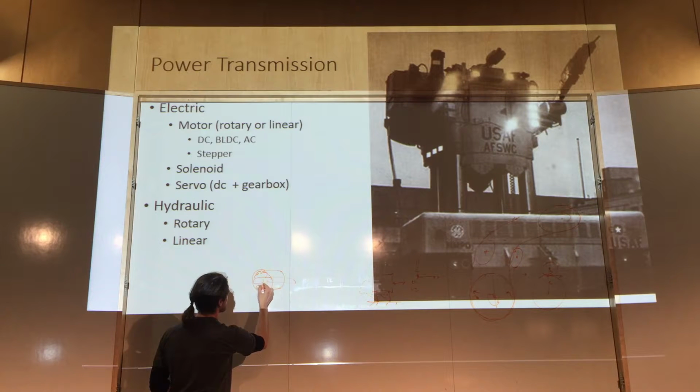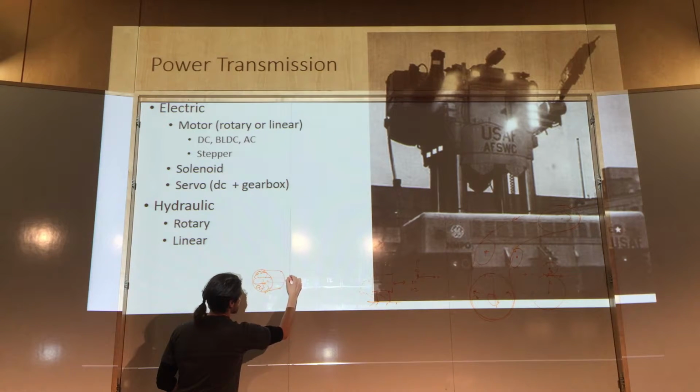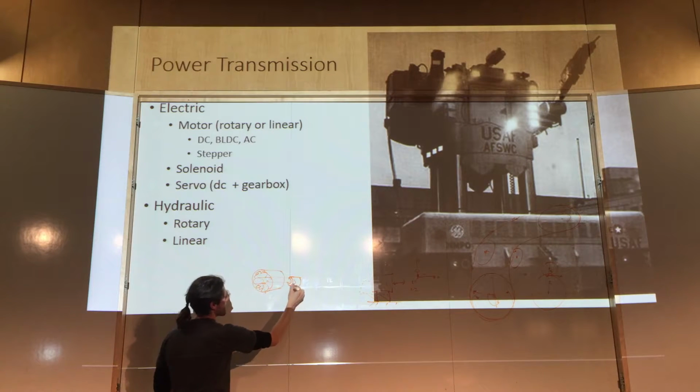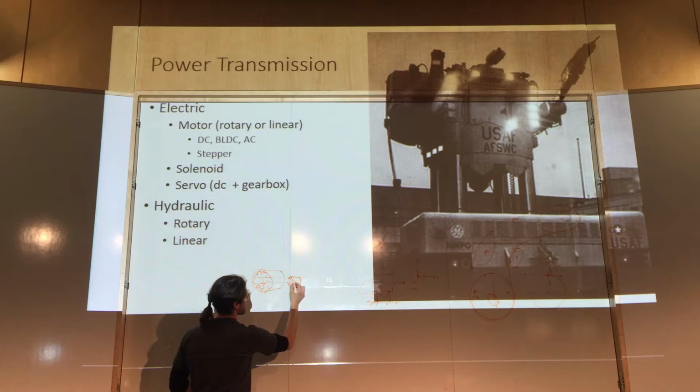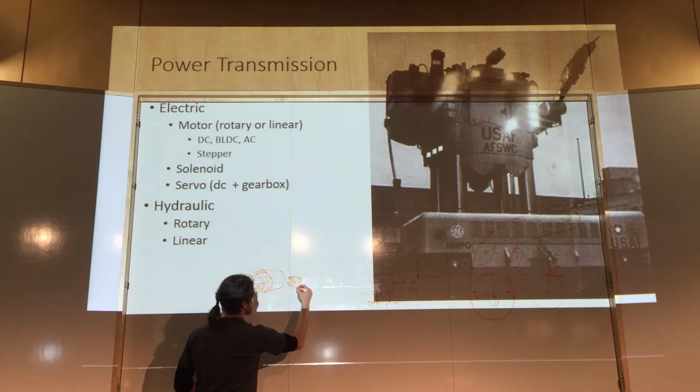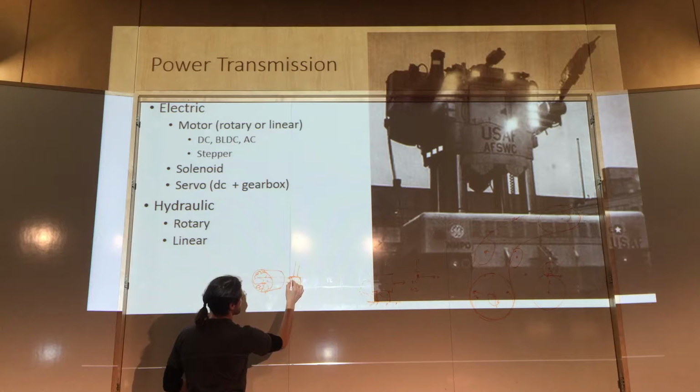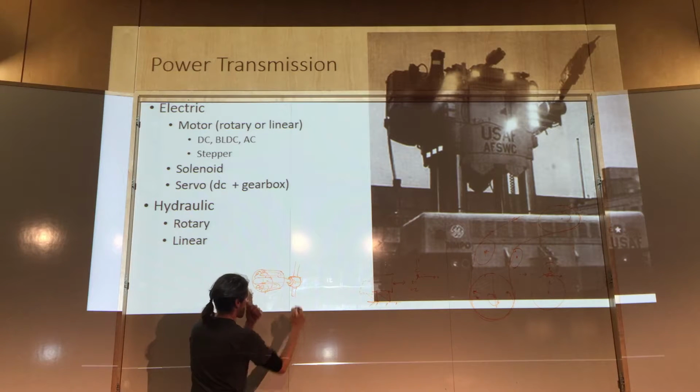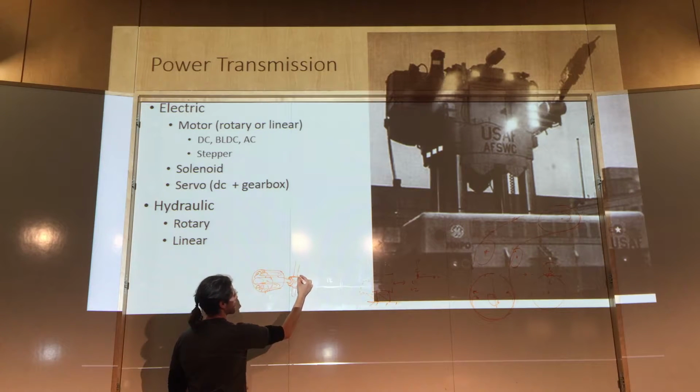But you've got your magnets in there, you've got your coil in there, and usually there's a set of something called brushes. You get commutation from having brushes that are attaching to contacts that are sending power to the coils inside the motor that are generating the torque. And so it's literally a mechanical system.